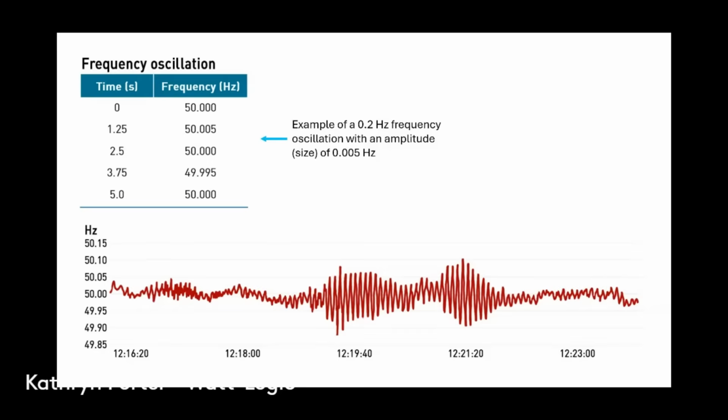Anyway, at around midday, a different frequency oscillation emerged, and that was at 0.6 Hertz, so a faster oscillation. And this was deemed to be unusual. And again, there was also a drop in voltage associated with that frequency oscillation, and the voltage also began to oscillate. So this meant there were waves of high and low voltage rippling through the grid. And these oscillations can make equipment behave unpredictably, which is essentially what the problem was in Spain. So Red Eléctrica observed the drop in voltage and really targeted its efforts on addressing that voltage drop, didn't really do very much about the oscillations.